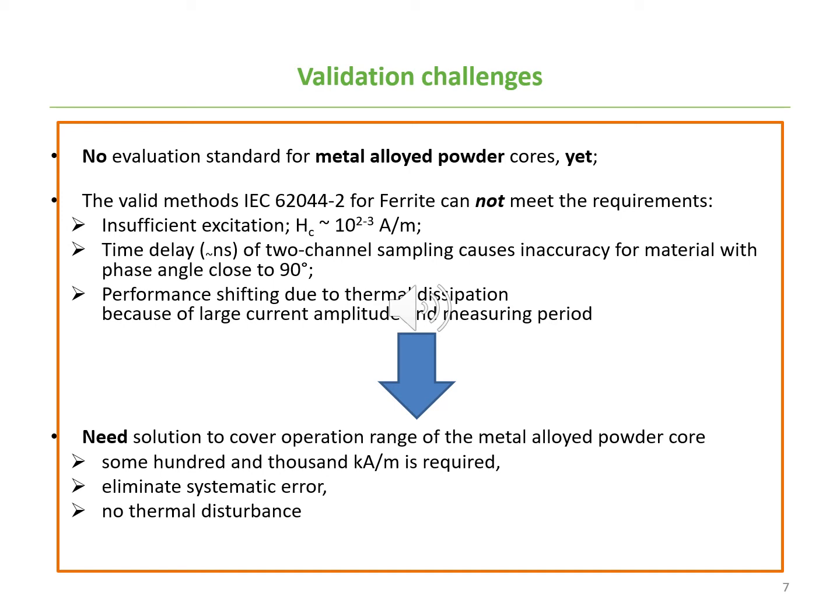And the metal alloy powder core with the same composition comes in different degrees for the desired permeability level, like 26, 40, 60, and so on. And it's very difficult to characterize this with one composition. People need different field strengths to see the same flux density point, because this is related to the definition of the effective cross-section. What people measure are voltage and current. What people talk about and characterize are Tesla and Oersted.